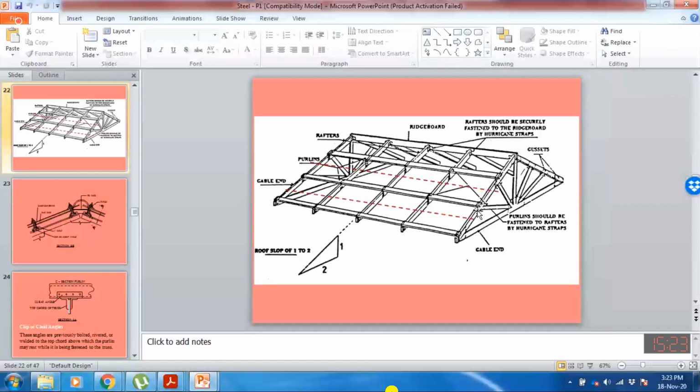But we also provide some projection of the sheet on this side. So this is the end projection that we need to add. So this length is equal to half length divided by cos theta plus E, multiplied by the spacing between trusses or the length of the purlin. That will be this area.